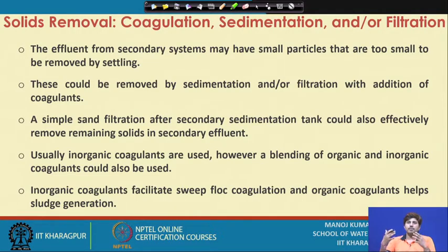That removes the microorganisms which grow in the biological units before secondary settling. So, whether it is a trickling filter or an activated sludge process, those biomass are settled in the secondary sedimentation basin.